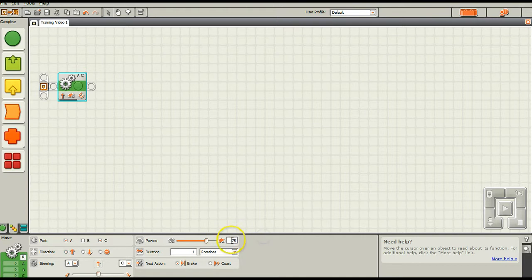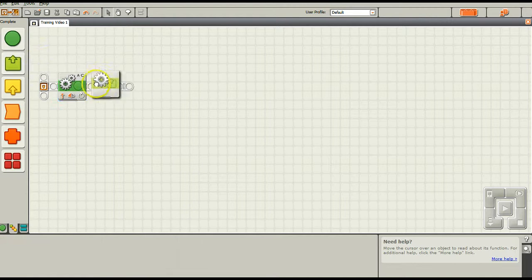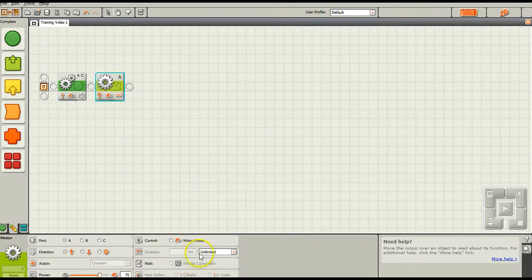Again, we're using the bigger wheel, so I'm going to set my 50 power. We're going to go, let's say, 720, we're going to go 1440. We're going to go basically 4 full rotations, and then I want a hard brake. All right, then what I want the robot to do is a single wheel turn. I want the robot to turn 90 degrees.